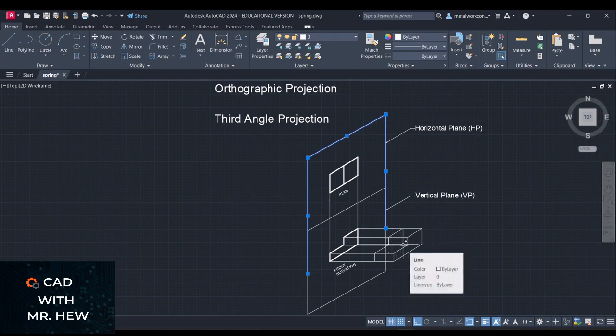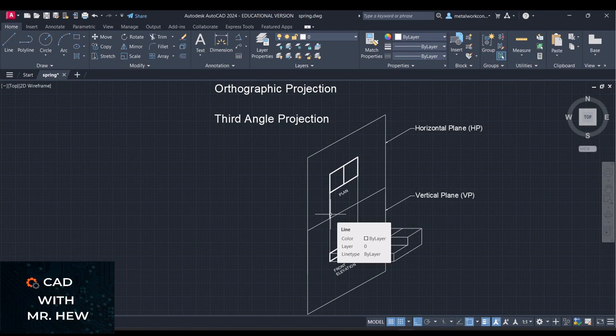Now this is a model, so you don't normally draw the three-dimensional model with the two-dimensional third angle projection or first angle projection. This is just a model. I started off with the four quadrants. This is when it is removed from the quadrant and the horizontal plane is folded up, so that is why the plan is at the top.